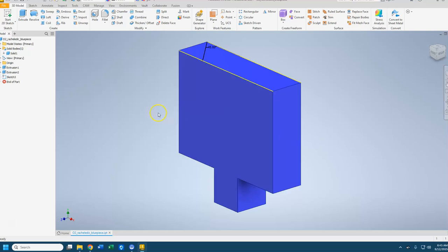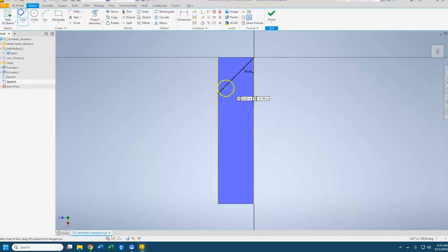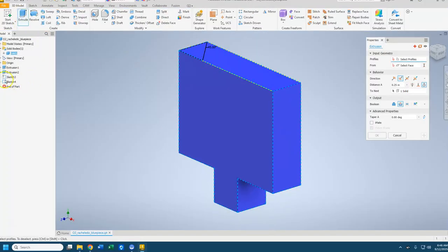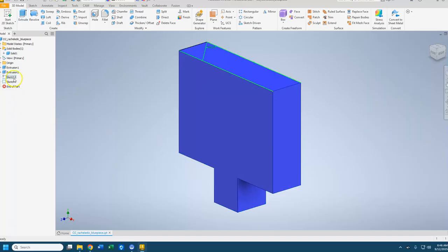Still don't follow along. Something else I do want to show you. If I go, okay, I need to close that, it has to be in the same sketch. So I'm going to come in here, I'm going to draw the rest of that triangle. It's still not going to let me extrude that because I've now drawn those two parts. I've drawn this line and these two lines in different sketches. So they're not going to interact with one another because they're on essentially different layers.